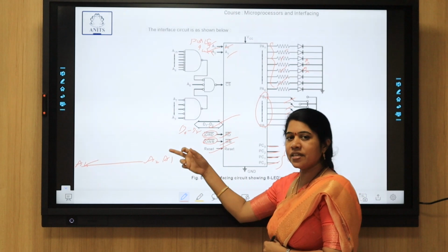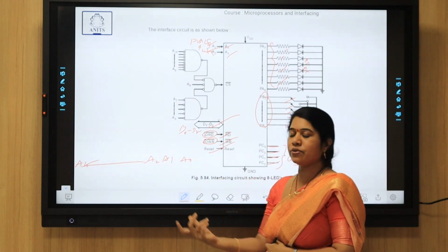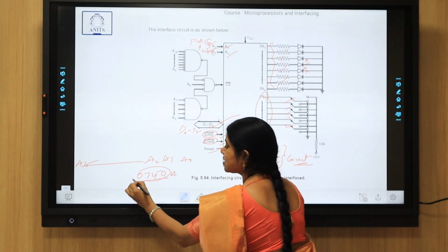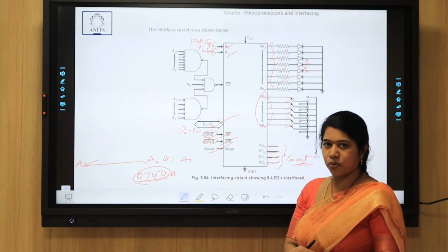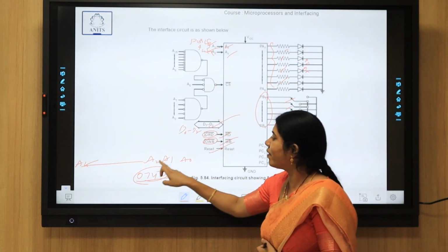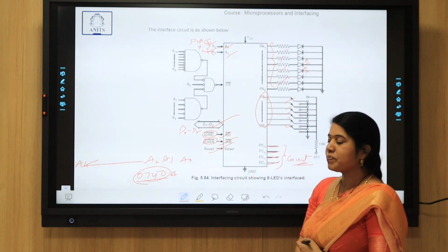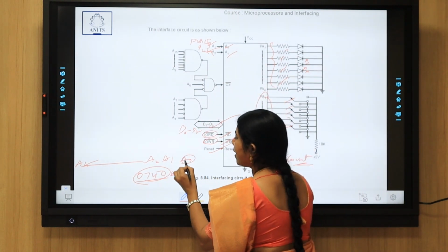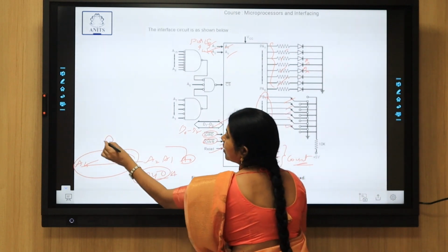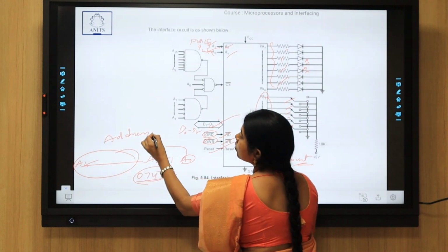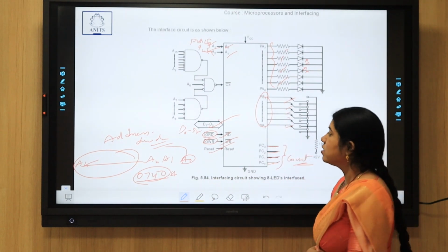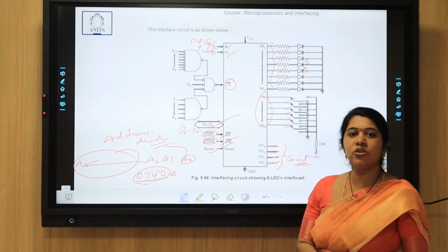As we have seen in the previous slide, all the address bits are used, because the port A address is selected through 0740H. A total 16-bit address is required to select the ports. Yes, the processor has to send the entire address, but based on A2 and A1 lines, the corresponding ports will be selected. So we have to use the remaining lines for selecting the chip through the address decoder. Yes, the address decoder is the decoding logic that is used to select the ports through the chip selection. That will be connected to the chip select.